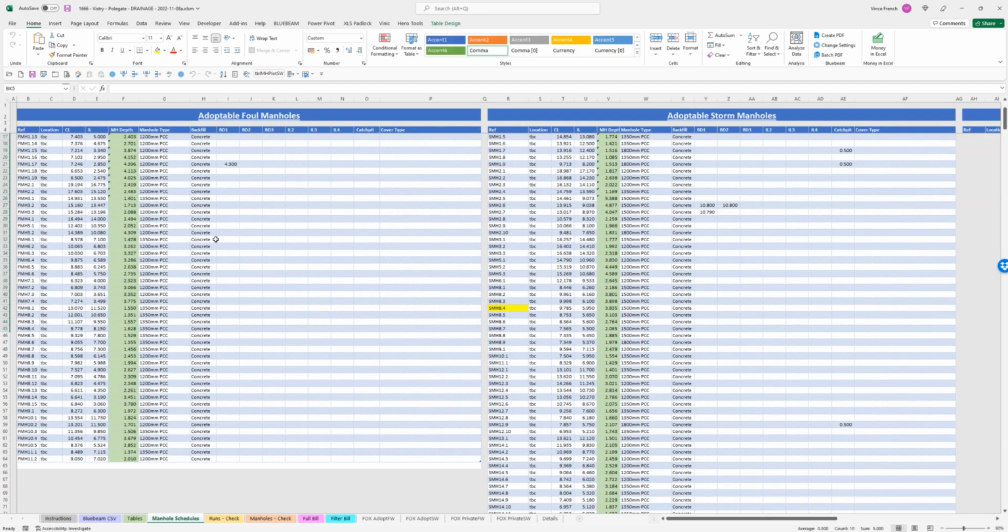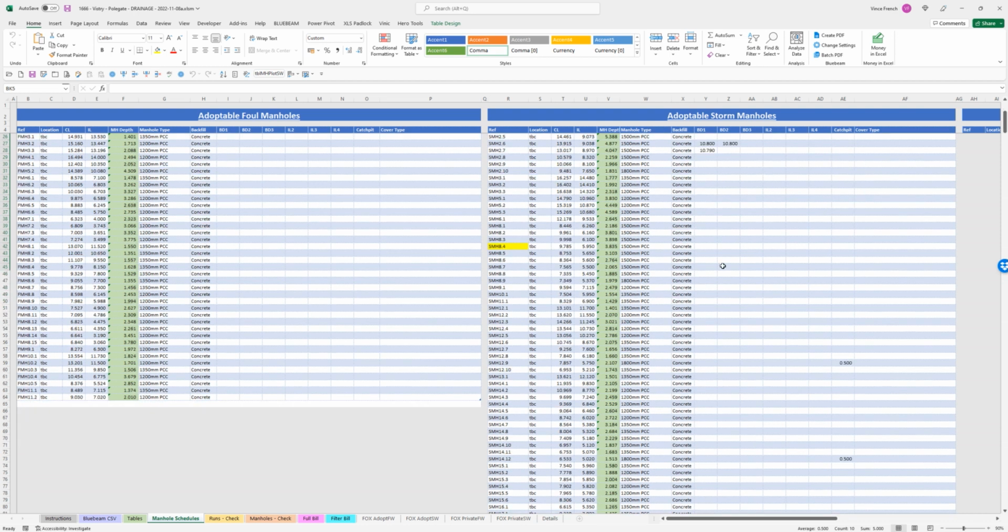We've then got a manhole schedule. Hopefully the engineers provided us with a manhole schedule. We can put our locations in here. We could put road numbers in just to break this down further, but I haven't done that yet. Cover level, invert level, manhole type, what the backfill is, and whether we've got any backdrops, what the levels are for those. Over on the storm, we've even got catch pit details, depth of the catch pit.